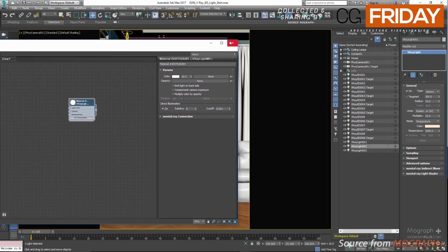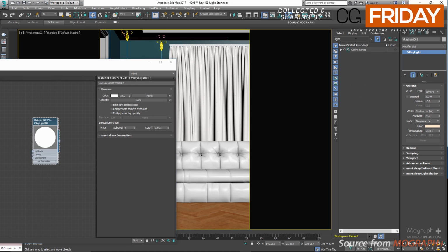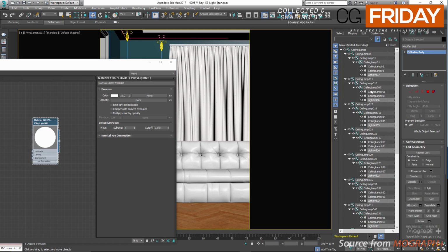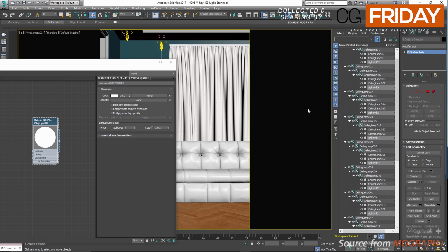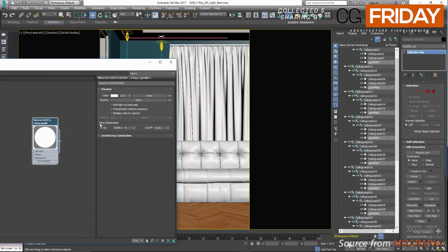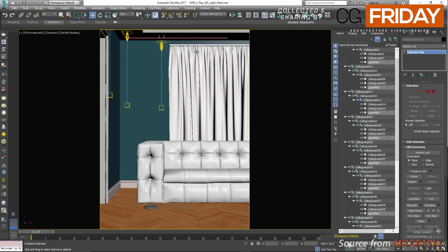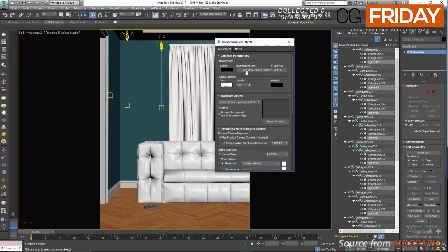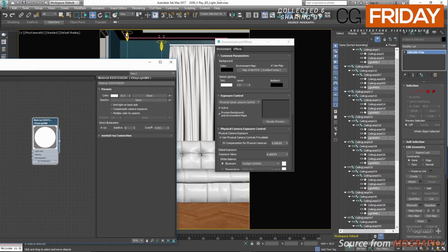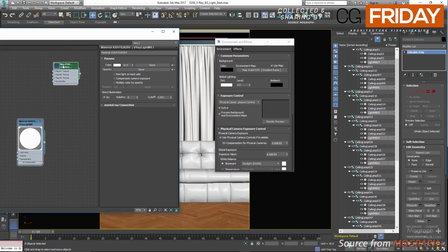Now I have renamed the parts of the light that I want to apply this V-Ray material to light MTL, just so I can select them more easily. So type light MTL in the Explorer and press enter to select them. Now assign the material. Also, if I open up my environments and effects window, as you can see, I have this gradient ramp as the environment map, and if I instance it in the material editor, you can see it's a very simple map.